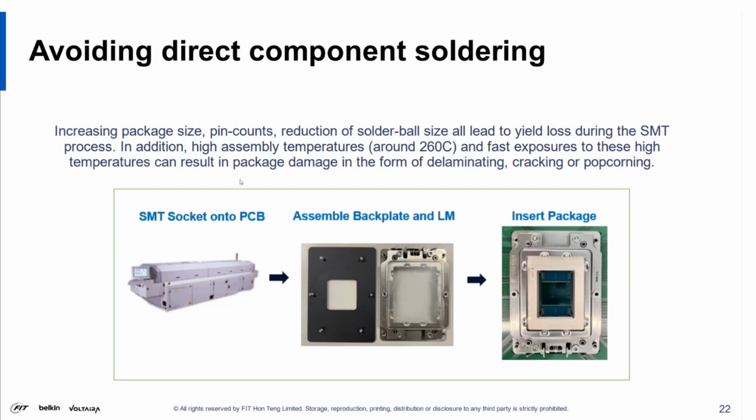So when you decouple the SMT of a direct attach chip from your system, you don't have to worry about any of the solder joint problems that exist today when you are trying to reflow all of your components on at the same time. Okay, and you don't have to worry about customized temperatures.